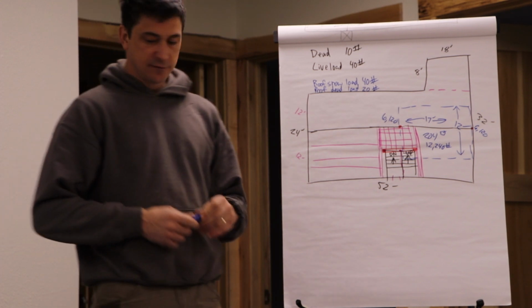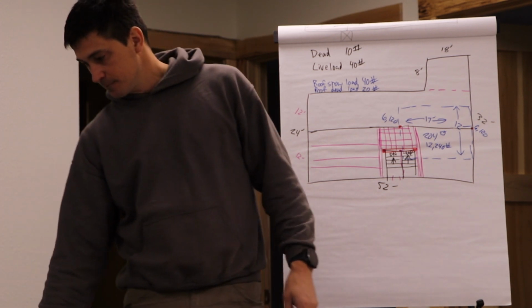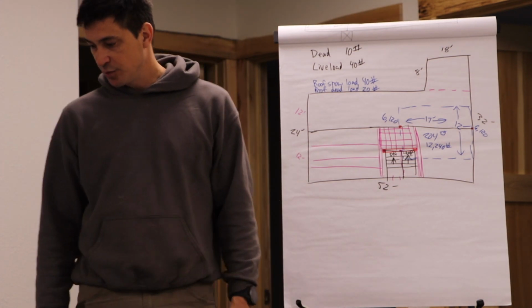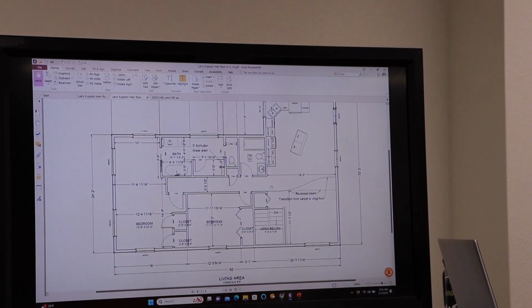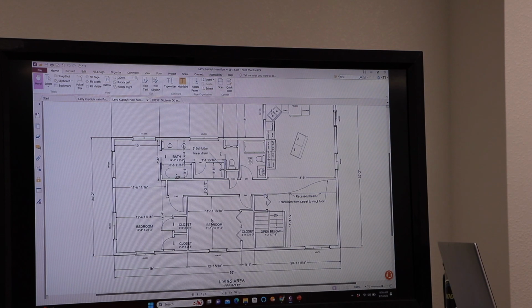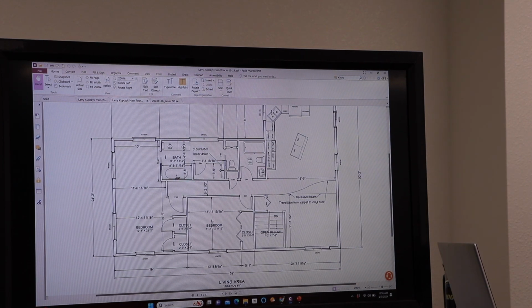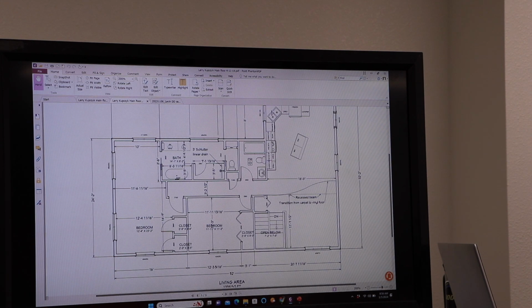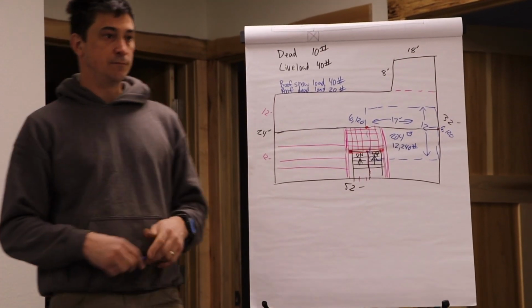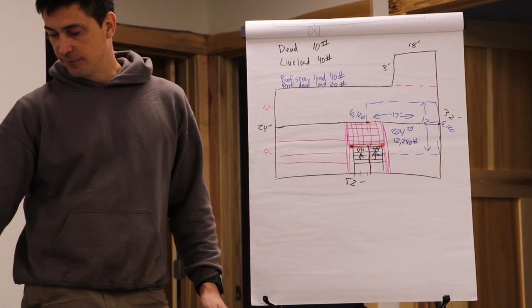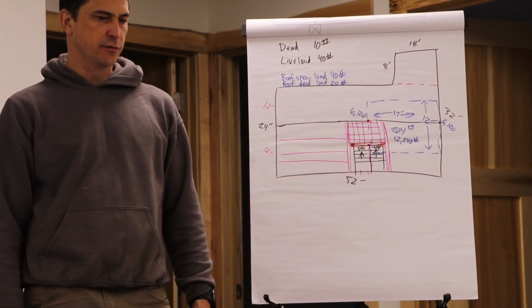And so you've got to be able to look at this plan and be like, okay, I can see that right here I need to have a footing in my basement because I'm going to carry a load on there. You should have a building designer that's making that note, but you're the last one to catch any mistakes or anything that's missed. And so you flip to your foundation plan and like, oh, there's no footing in here.